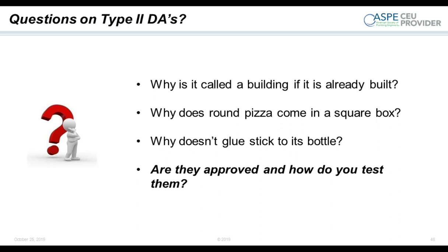So let's address this, because one thing we see a lot of, and I think one of the reasons that type 2 hasn't caught on the way it really should have, is that if you're a tester and this wasn't covered in your testing course, and I can tell you it wasn't covered in mine when I got certified, and you walk up to these valves, you might fail it because you see a bypass, you see a single check in the bypass. In your head, you say there should be a full backflow preventer in it. You fail the test, and then we go through a whole thing where maybe it gets pulled out, maybe you end up calling someone like me, the manufacturer, another person has to get sent out. It's not great for anybody involved, right?